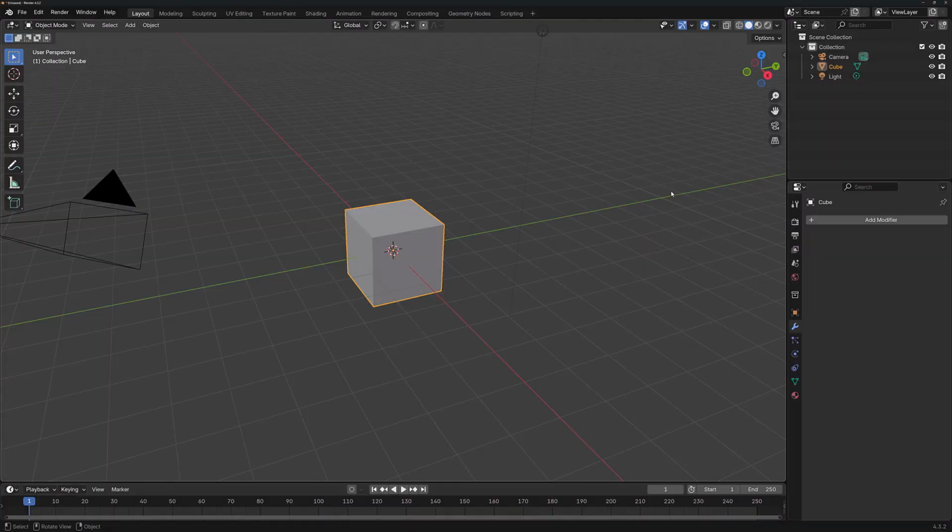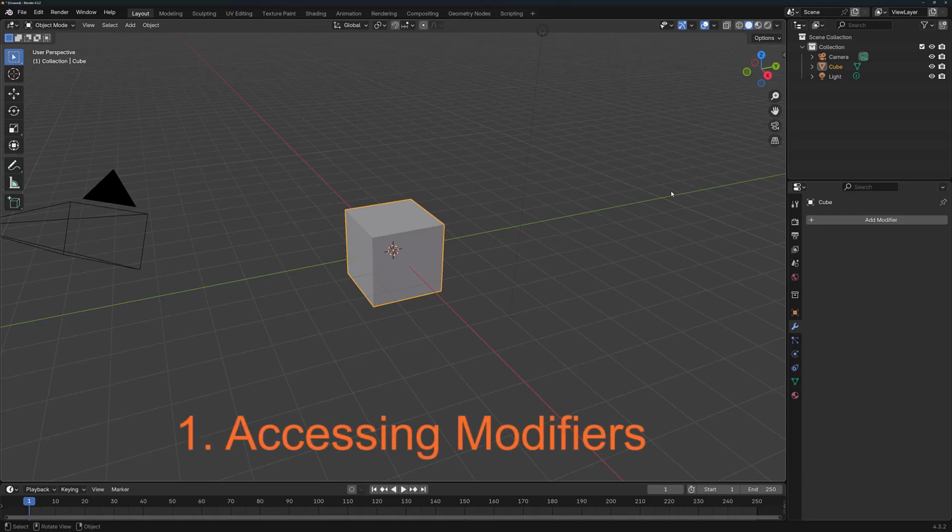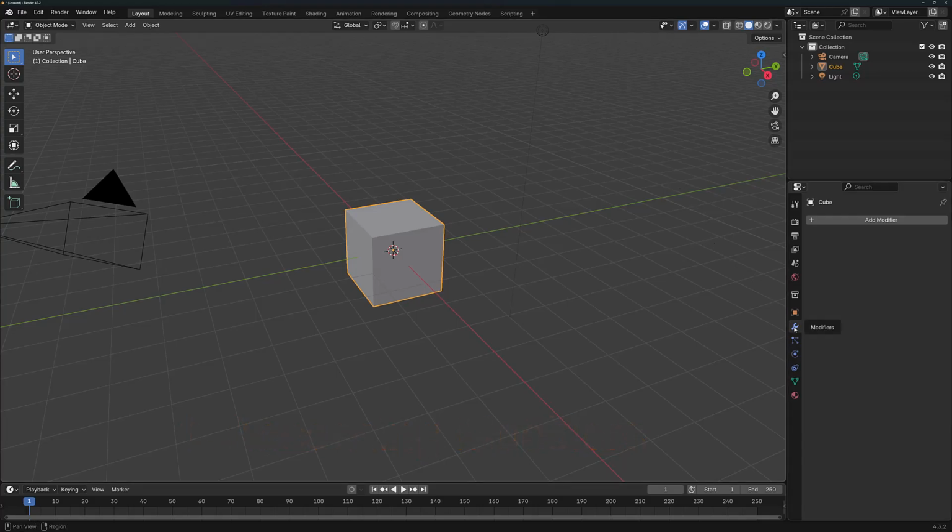With the help of the Subdivision Surface Modifier, we can add a lot of geometry very quickly to any object, whilst also being able to smooth out the topology of our models to create a more natural, cohesive appearance. To access the Subdivision Surface Modifier, go to the Modifiers tab in the Properties panel.